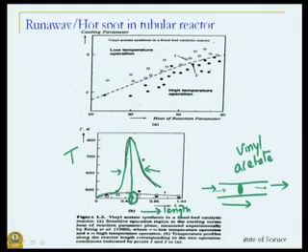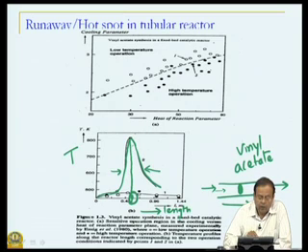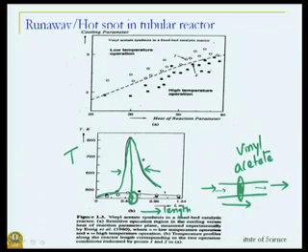And just imagine a scenario in which your reactor is made up of a material which can withstand only about 700 K, because you are going to operate it at 500 K or below 500 K. So, you thought to give a safe margin: let us make a reactor which can withstand up to 700 K. And look at what will happen if we have an operation like this. We will have temperatures reaching as high as 800 K, resulting in complete meltdown of this material, because its melting point is only about 700 K, and then you never know what will happen if the reactor melts. A sure recipe for an accident.